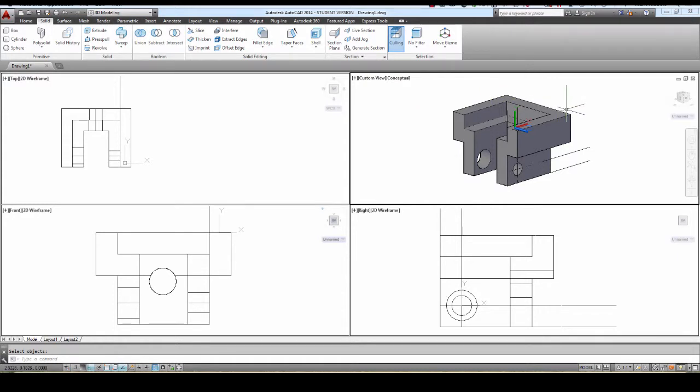So when I come in here and I use the fillet command, I pick my solid first, like this, and then it's going to ask me my fillet radius, and I'll go with a 0.5 radius, okay? So that's asked me to select the edge, okay? So I want this edge right here, okay? And when I hit enter, it fillets that. Now notice it filleted that first edge that I picked too, so you have to be careful about that, okay?